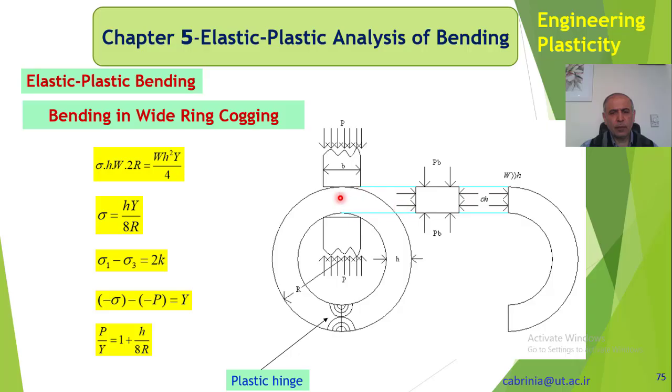So it's easier to flow this way, and that is what happens. But when this W becomes smaller, not very much bigger than H, then the material also flows perpendicular to the screen and also in this direction as well. So in three directions, X, Y, and Z. But here only X, Y, it cannot flow in the Z direction.